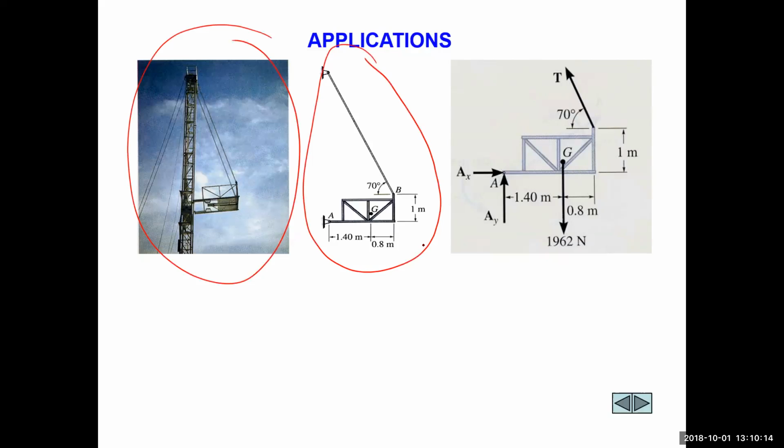And then we turn it into a free body diagram, right? So this is the free body diagram. The free body diagram has everything you need to know to write the equations of equilibrium. Okay, notice all the angles that we need are there. Even if the angle's somewhere else, you got to put it on the free body diagram to make it correct. Okay, so that's showing you the forces, at the pin, the force from the cable, the force of the weight, all the forces acting on it.